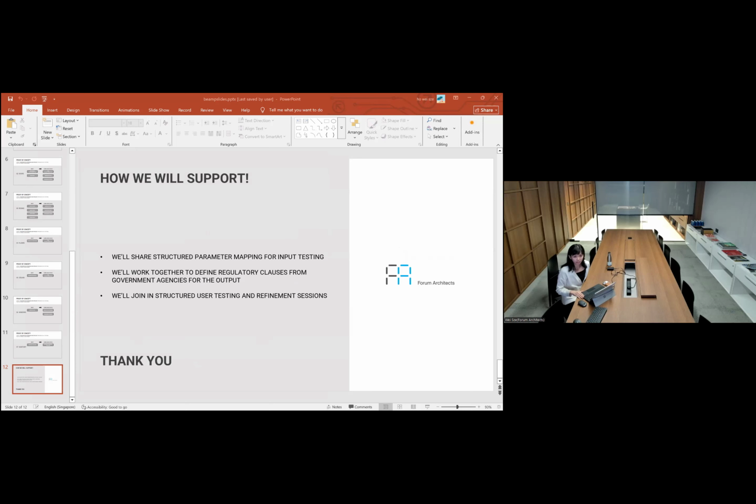So in our office we use Revit as our main software for modeling. The way it is being structured now would be from the Revit model we model already, and then we have to change all the families to IFC parameters to export out as IFC data, as an IFC model.